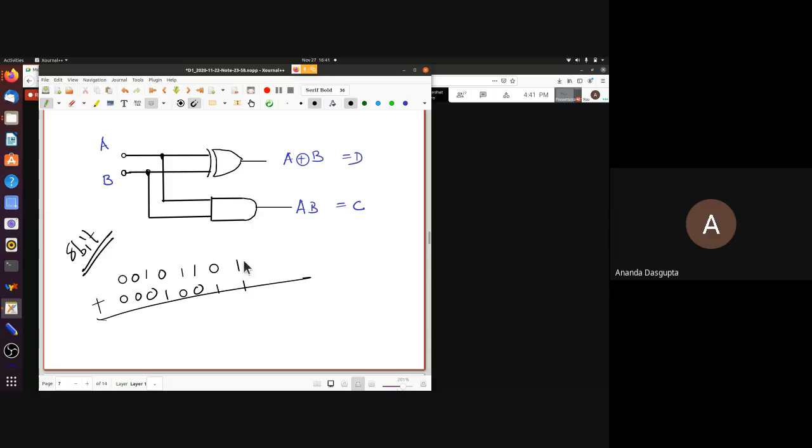Simple. You add them, 1 and 1. What do you get when you add 1 and 1? You get 0 as a sum, and you get 1 as the carry on the other side. You actually get 2, right? But 2 is 1, 0. So it's just like when you're adding 73 to 98: 3 and 8 give you 11, but 11 can't fit there, so 1 gets written down, and 1 gets carried. Similarly, 1 and 1 gives you 1, 0. So 0 goes down, 1 goes up here.